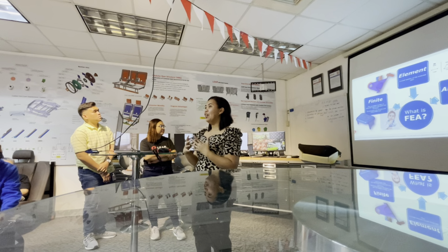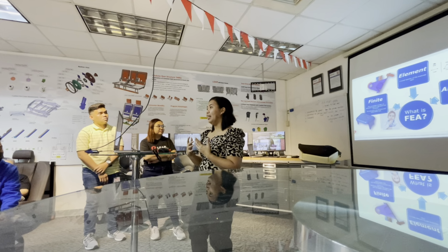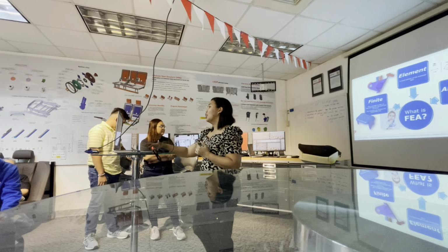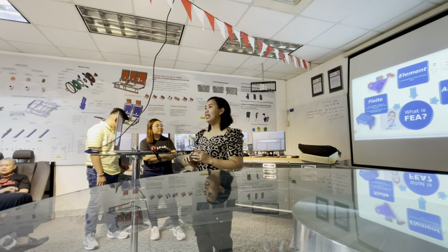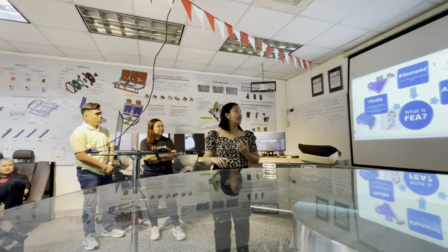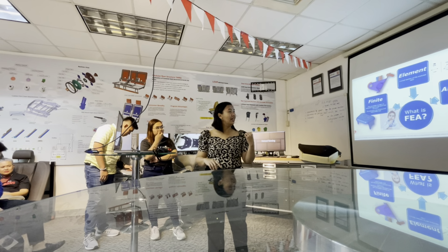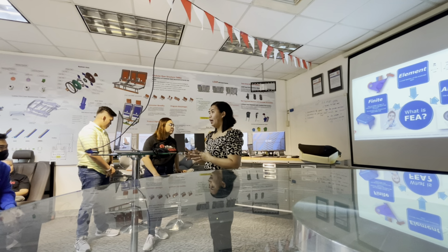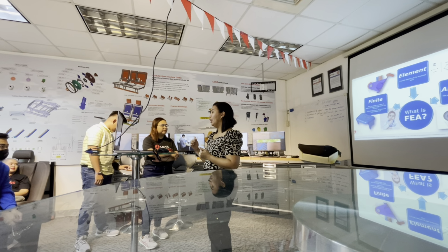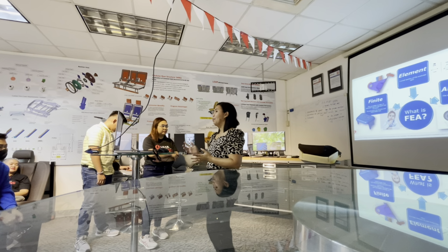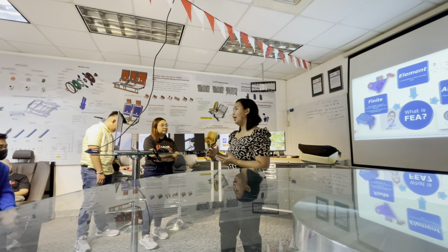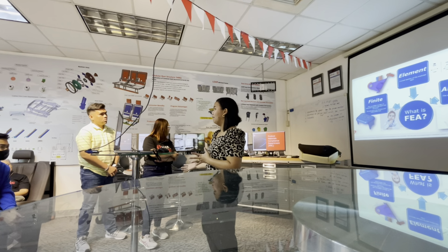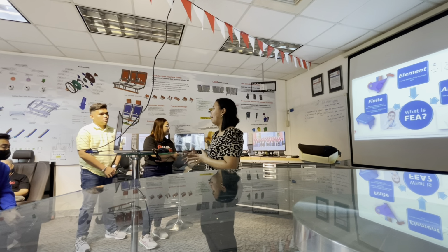Depending on the complexity of the part, say a stamped part or a part with a uniform thickness, they are represented by 2D elements, these triangles and quads. And for geometries like foams and plastic parts, they are represented using 3D elements: the tetrahedron, the hexa, and the penta. It's called analysis because we subject the part to boundary conditions, we put loading conditions, and then we analyze the part. So basically, FEA is representing a numerical or mathematical model, understanding its effects during the product life cycle. It's like predictive analysis of what happens to the part.